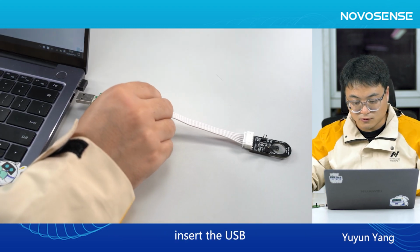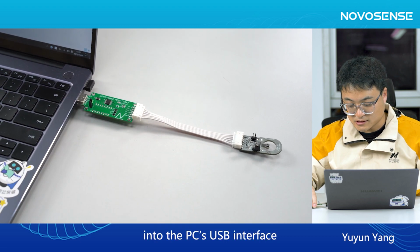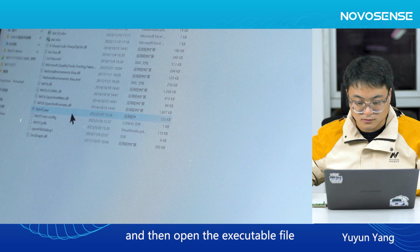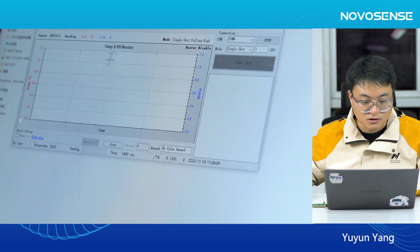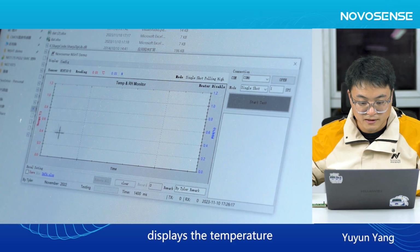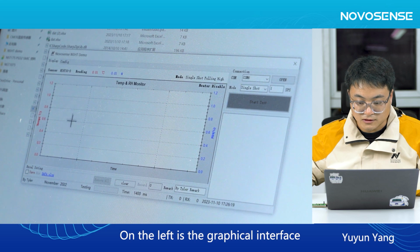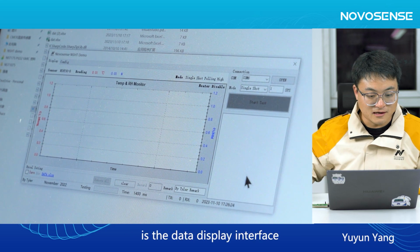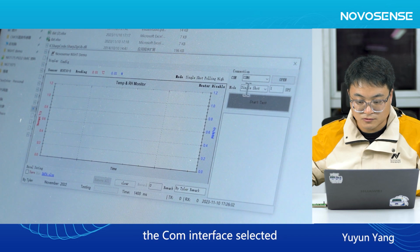First, insert the USB for our temperature and humidity sensor's MCU into the PC's USB interface, and then open the executable file in the upper computer. Upon opening this file, we can see that the first window displays the temperature and humidity data. On the left is the graphical interface, and the right is the data display interface. At the top right corner shows the COM interface selected.